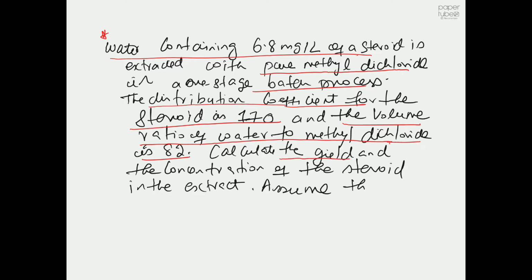And then what I asked you is to calculate the yield. I think we already did something. Instead of yield, I asked you to calculate extraction efficiency. Both refer to the same. So we will calculate the yield, and then I also want to know the concentration of the steroid in the extract.